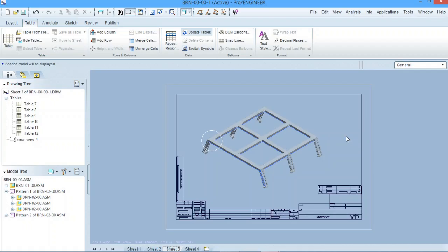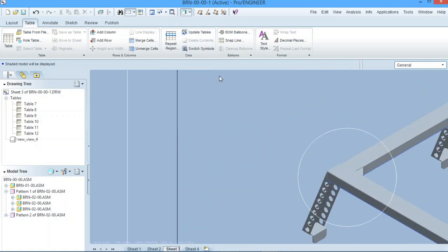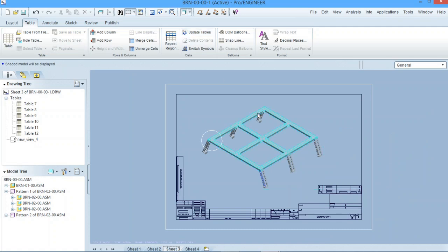Okay. Now, nice little feature, extra feature is if you want to zoom correctly and you want the whole page, the whole drawing zoomed, you can zoom extents up here. Click there. See there, it's quite nice. It brings it into the limits of the actual drawing. So that's always a nice little feature.